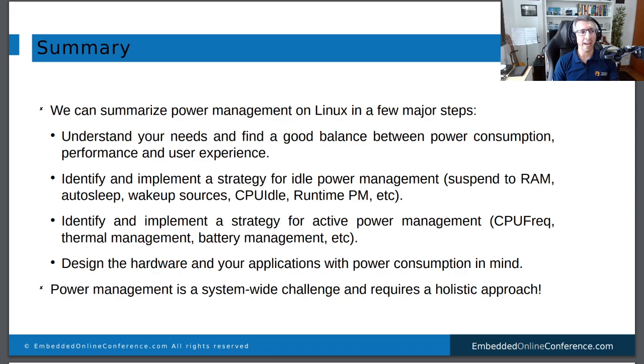And what about active power management? Do you want to get the CPU into a lower frequency? You might want to impact performance. Is that okay in your use case? Do you want to manage the battery if you have a battery connected? Do you care about the heat generated by the SoC, for example? Do you want to manage that? You have to keep everything in mind when you are designing this system.